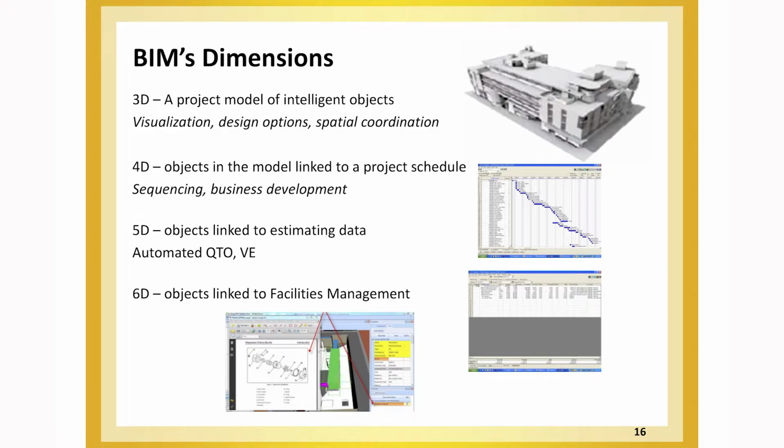We've taken it a step further, where we have 3 levels of LOD, because on the projects that we work on there's confidentiality about what goes out. The reality is that Department of Buildings inspectors don't need to know what the widget is. They just need to know there's a widget. So we have card reader detail going to the contractor, high-level detail feeding into Maximo facilities management, and the building permit set that we share with everyone is just a circle with a key code. You need the key code to know what the device actually is.